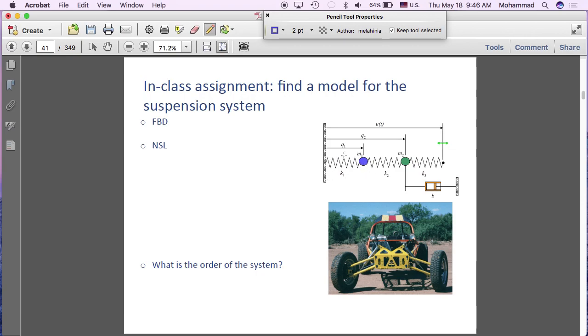And this is the deflection of the chassis itself. So we have the deflection of the sprung mass, the unsprung mass. So we are basically capturing the behavior of this physical system, or a corner of this physical system, we should say, 1/4 of this car go-kart with this model. So 3 energy storage elements, 3 springs, K1, K2, K3, an energy dissipation element as a viscous element B with constant B. Input, we call this U of t as input to the system.